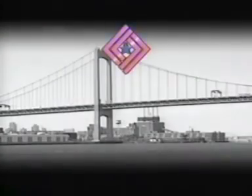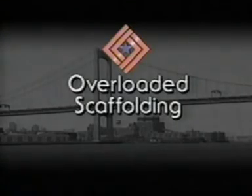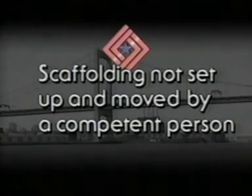A company spokesman said both workers were wearing safety belts, but neither had his belt attached to a safety line when the accident happened. Six months after this tragic accident took place, OSHA issued a citation alleging that the employer of the two men committed the following willful or serious safety violations: overloaded scaffolding. The scaffold was moved while the workers were on board. The scaffold was not set up and moved by a competent person.